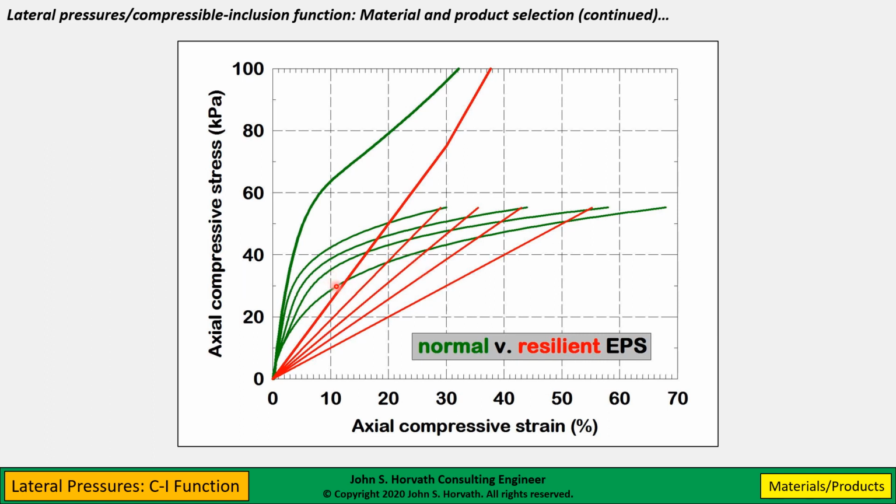So if we properly consider the behavior, not just under a test that is run in 1 minute or so, I mean, these tests here are 10% strain rate. These tests only took 2 to 3.5 minutes to run. So this is the 3.5 minute behavior. We'd be a lot better off to consider 10 hours, 100 hours, 1,000 hours, 10,000 hours. At a given stress level, look how much softer the material behavior is if we consider the creep.